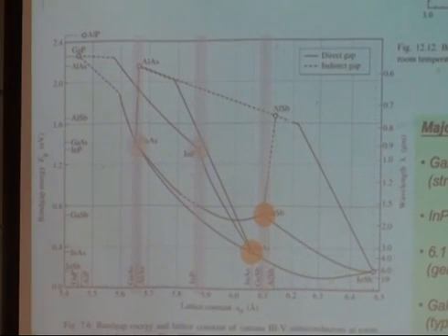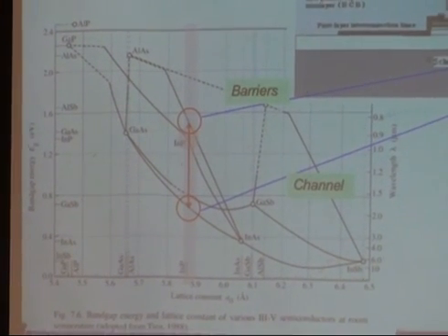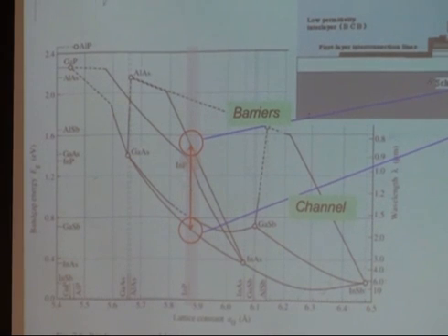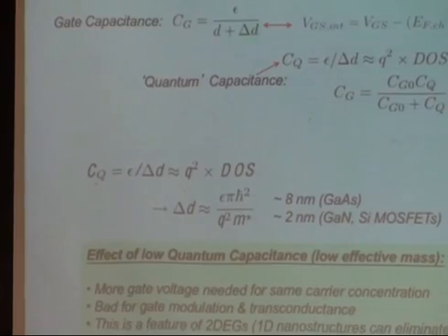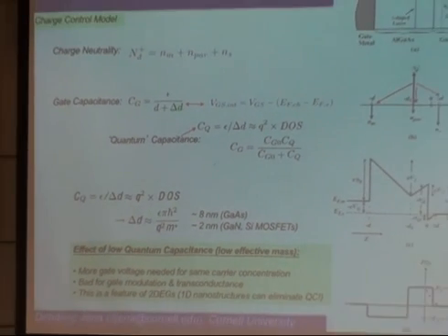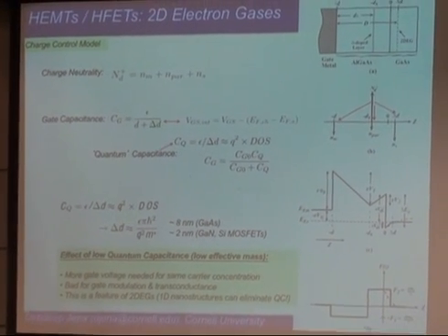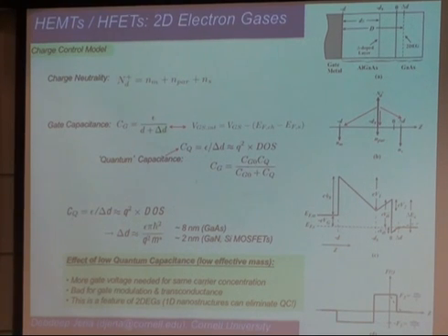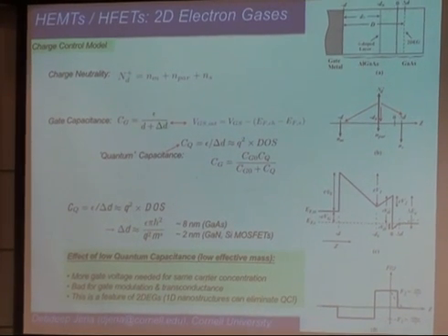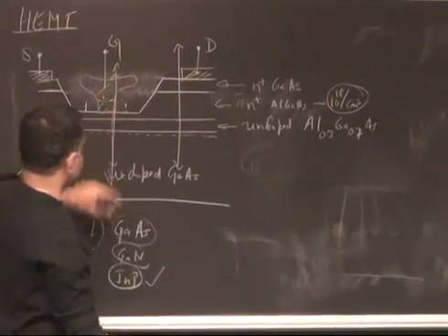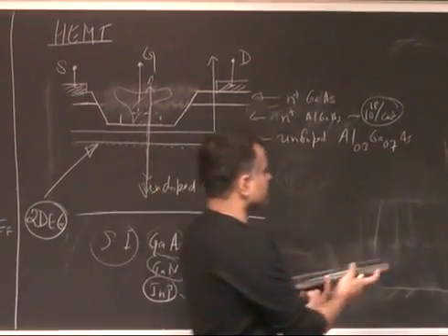Okay, so looking into the structure in a little more detail now, I wanted to run the simulations, and I will do that now. If I go into the structure along this region, I have n plus. I'm going to draw the energy band diagram along two directions. One is here, and the other is here. And we'll see why we have this region, because it will help us in the ohmic contact, and why we have this region, because it helps in the modulation of the transistor.